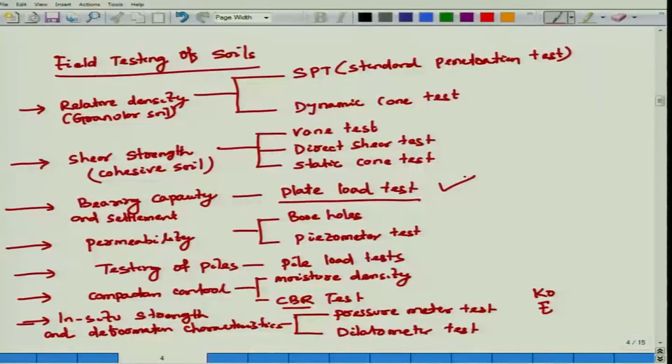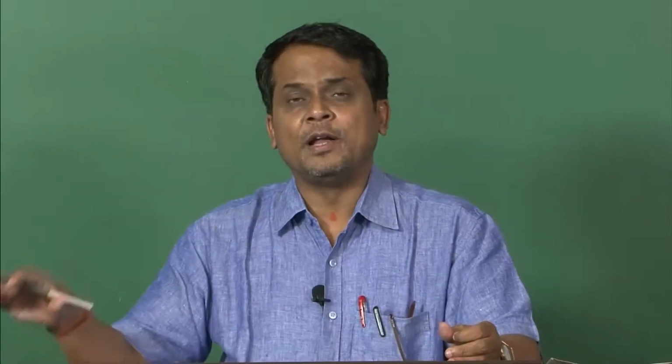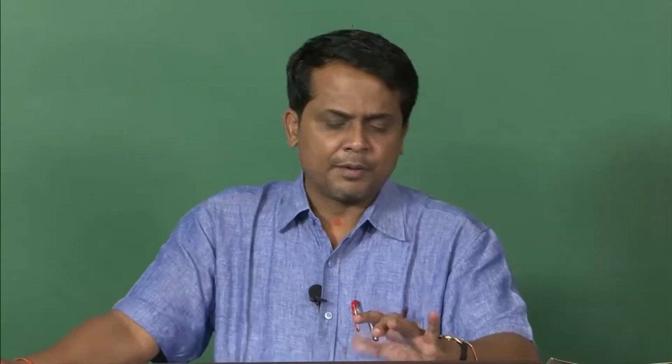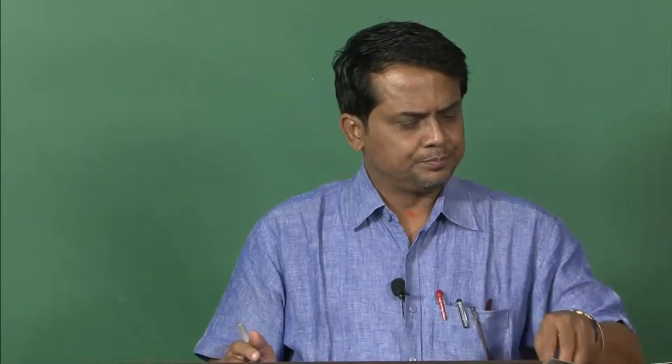Or, I will not do the standard penetration test, rather I will do one test, that is plate load test, that will give bearing capacity and settlement. So, these values will be required for your modeling, for your foundation design as well as analysis. That is why this has to be finished very briefly, so that my emphasis will be on foundation design as well as analysis.